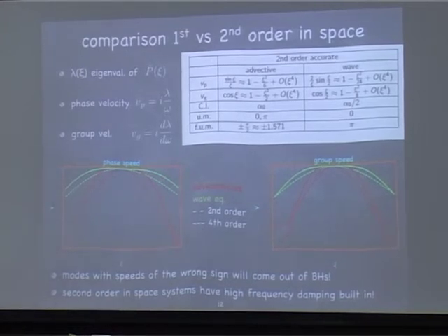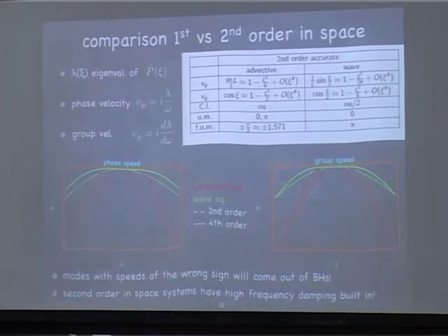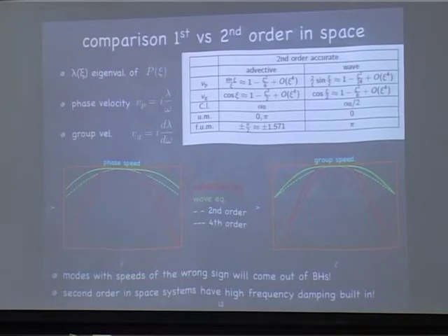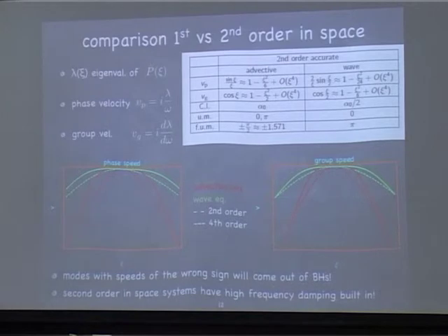But if we have a numerical scheme, we cannot expect that a numerical wave propagates with exactly the right velocity. If the wave is accurately represented, which means it has a low frequency, this is going to work well. But if the frequency is very high, if the grid is too coarse, your numerical wave is not going to propagate at the right speed. So the quantities to characterize this are, again, the phase velocity and the group velocity in the numerical setup. How do we compute them?